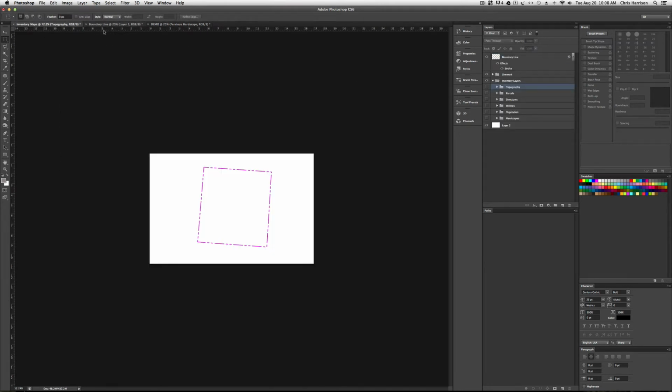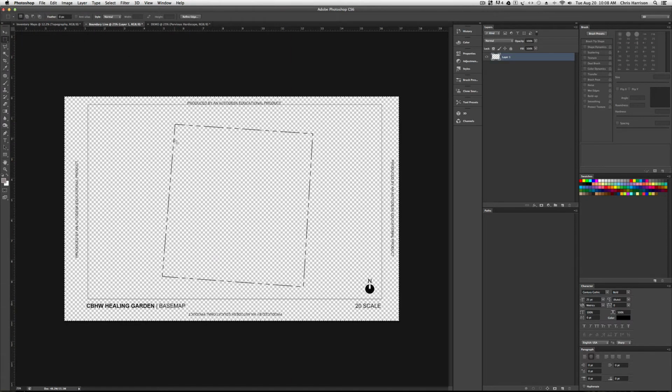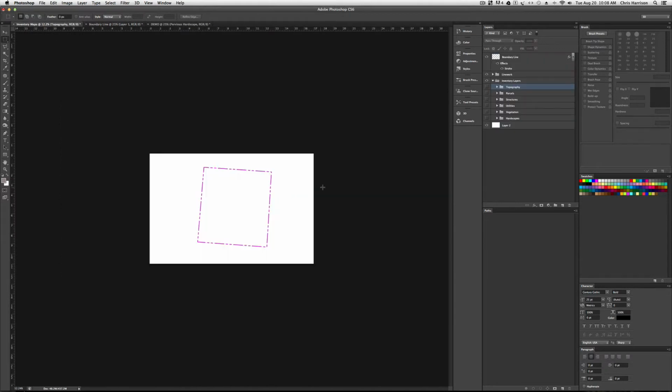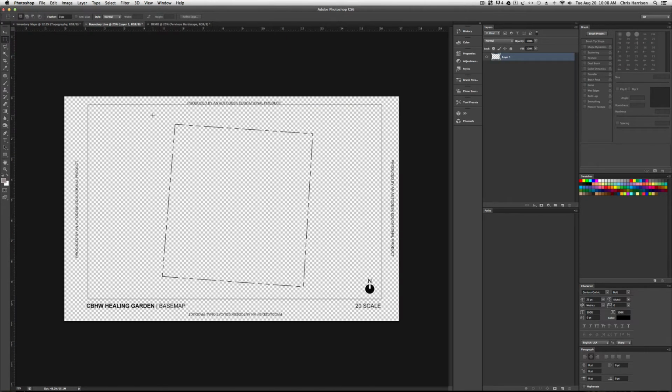And once you have one done, I'll bring in another one. So I have this boundary line, which is what you need to put in as well. You need a current marker. You'll see in this completed one that you have a boundary, so you give the viewer a reference. So regardless of what inventory layer that you're on, you have that boundary acting as a visual cue of where the site is. So that's the boundary line I have.